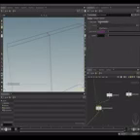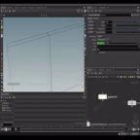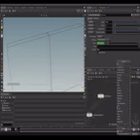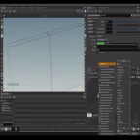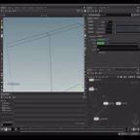Here I'm using the second contact geometry. And this is the constraint type, which can be a glue constraint relationship, hard, or you can also use the spring constraint relationship, soft. Actually, if you type constraint, you can see you have a lot of them. But for now, let's focus on these two.